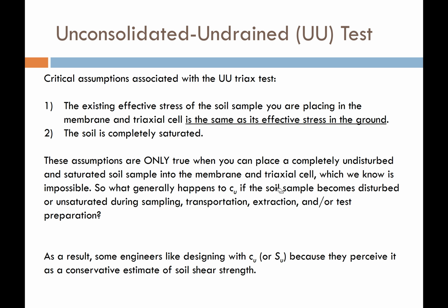Here's the truth of that. That's not going to happen. It's impossible. Anytime we sample the soil, transport it, extract it from the ground, or get it ready for the test, we're going to disturb the soil to one degree or another. And so because of that, these two assumptions that we're making aren't necessarily true.